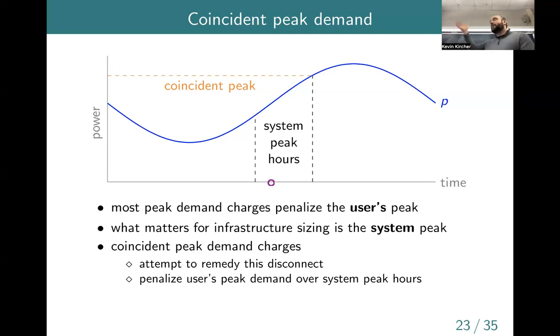You say, oh, okay, 2 p.m. tomorrow it's going to be the system-wide peak, so I'm going to pre-cool my building starting at 10 a.m., and then I'm going to raise all the temperature set points by a few degrees and coast through that peak period. In that way, you save maybe 100 grand by just doing simple logic for a big building. Anyway, it's useful stuff, but kind of arcane to think about.